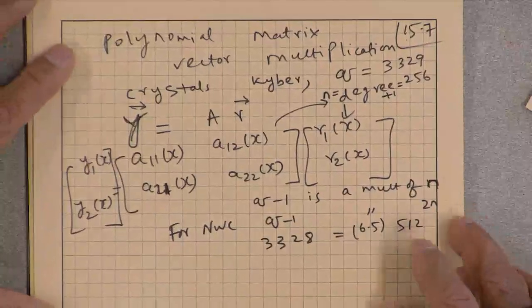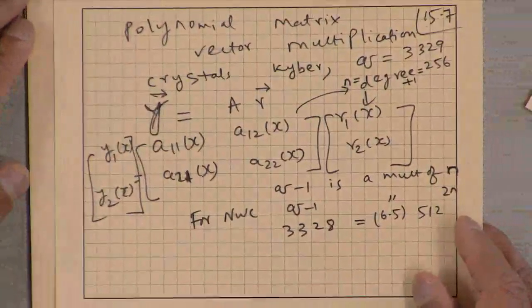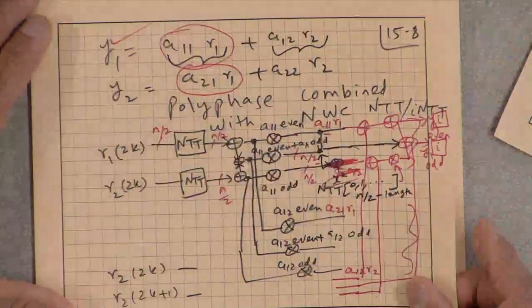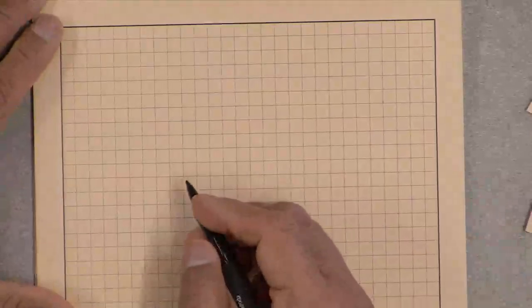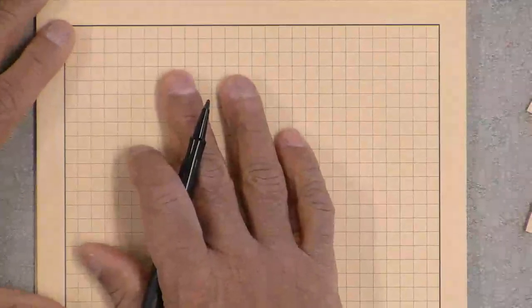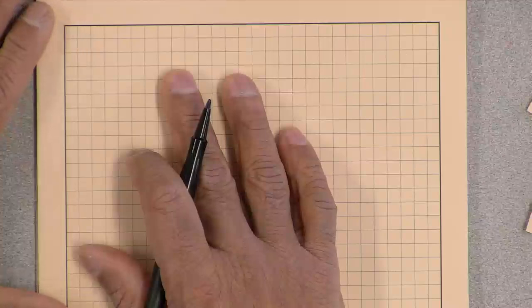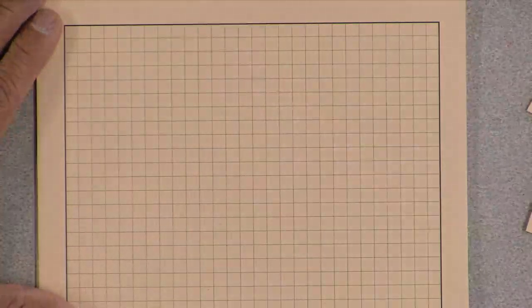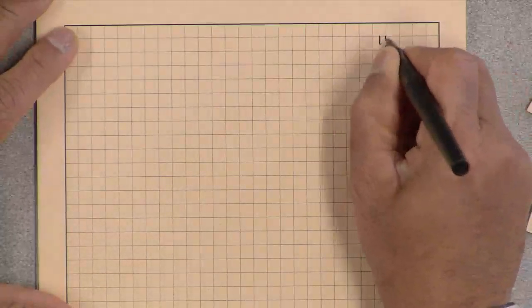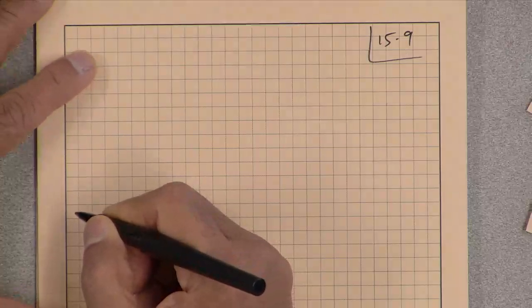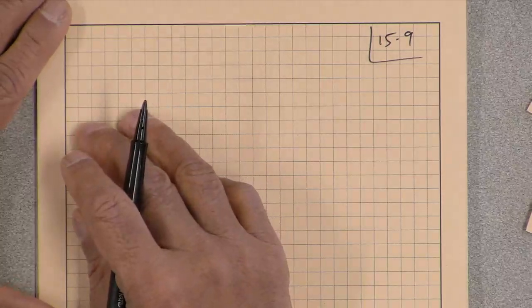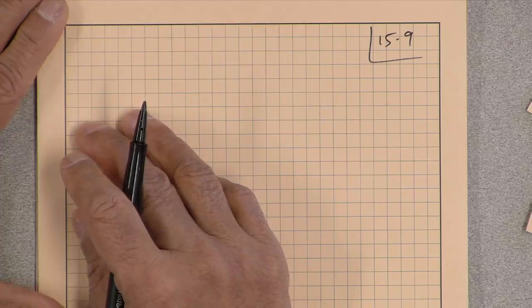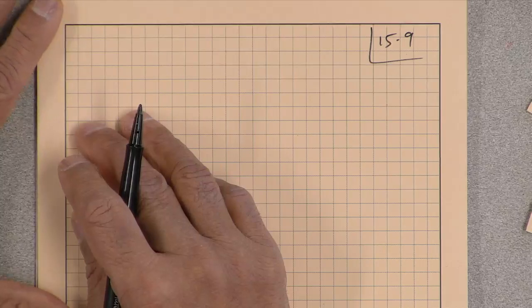So all of that, I think we have spent a lot of time talking about related concepts. If you think about this class as really fast signal processing, the word fast means reducing the number of multiplications, and that's really been our focus. So our focus so far has been how to reduce the number of multiplications. And for the remaining few weeks in the semester, we are going to deviate from fast signal processing to high-speed signal processing. High-speed signal processing means not just reducing the number of operations, but really increasing the clock speed and reducing the critical path, reducing the clock period, so that the clock speed and sample speed can increase.